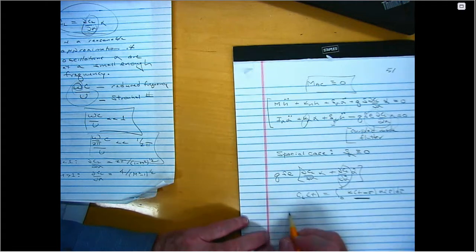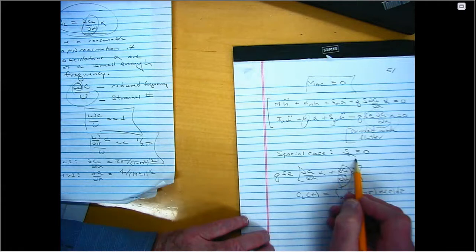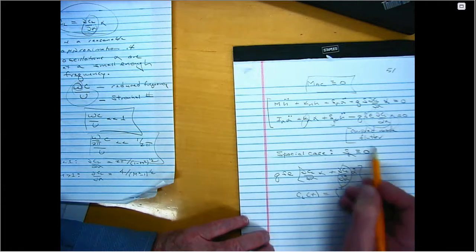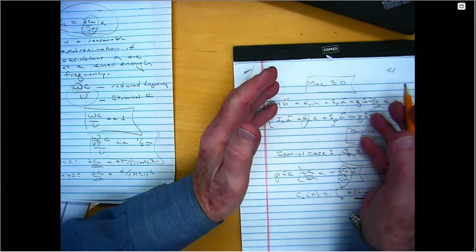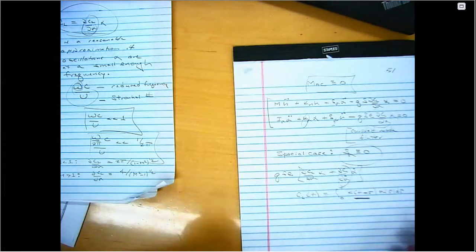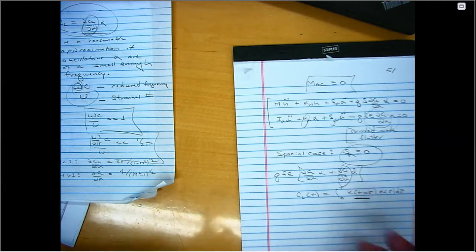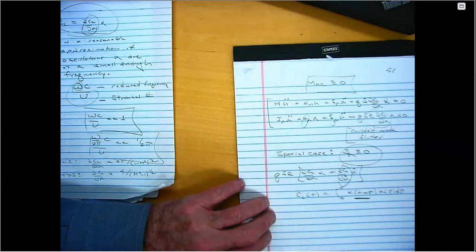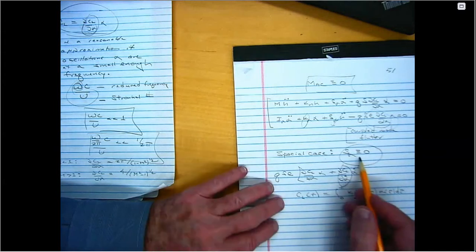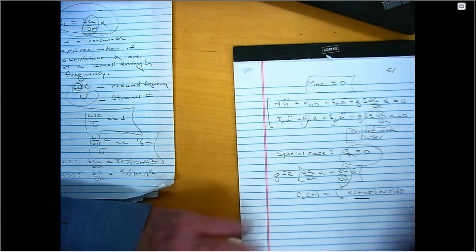All right, so what this tells us is coupled mode flutter never happens when this is true. And therefore, if you don't want coupled mode flutter, this is a famous condition for making sure, at least for this simple model, that coupled mode flutter doesn't happen. Now, sometimes the chief engineer will say, I'm not going to add that, it's terrible things from there, but you've got to come up with a better solution. So then there's a discussion. But this is something that people often look at. If the mass required to do this isn't too large, that's a good way to go.